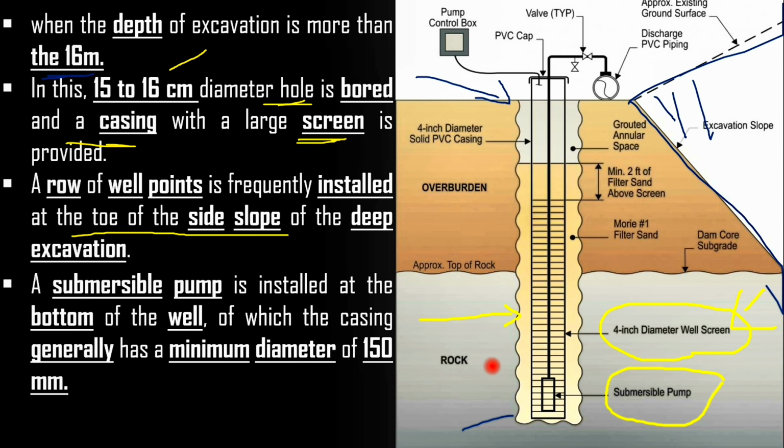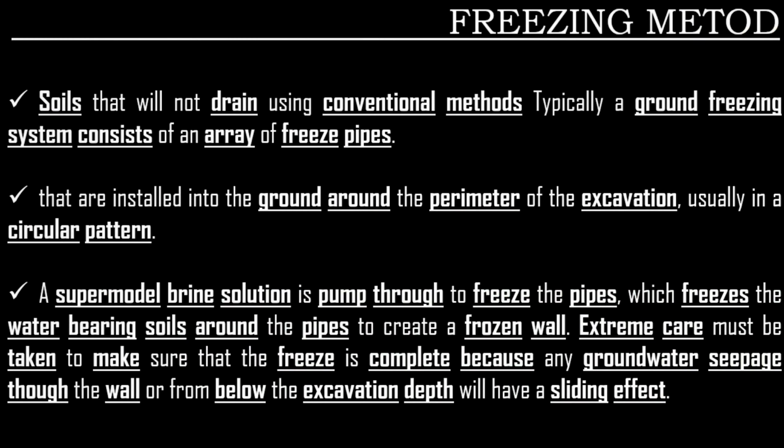The water comes out directly from this, and there I directly connect my pump. So each and every single well point works as a well point system. Because of that, it is very essential and the most used method in dewatering systems nowadays.